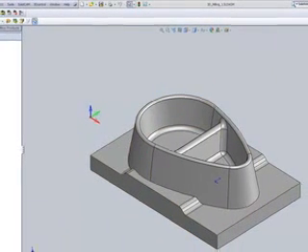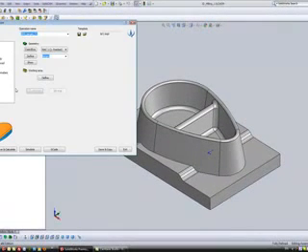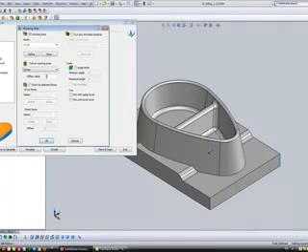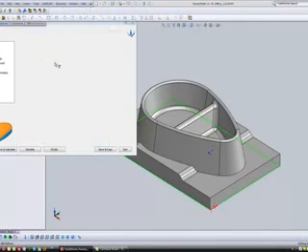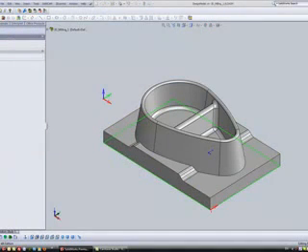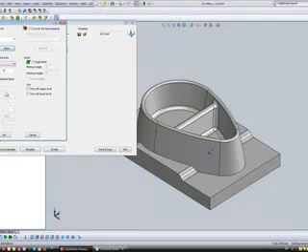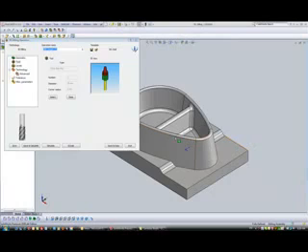If we open up our first operation as shown here, you'll see that we'll be using our target, and in the working area, our working area will be around the border of the part itself, working an offset of 10 millimeters out from the center of that part. I'll be using a 20 millimeter rough end mill to use on the rough cut.